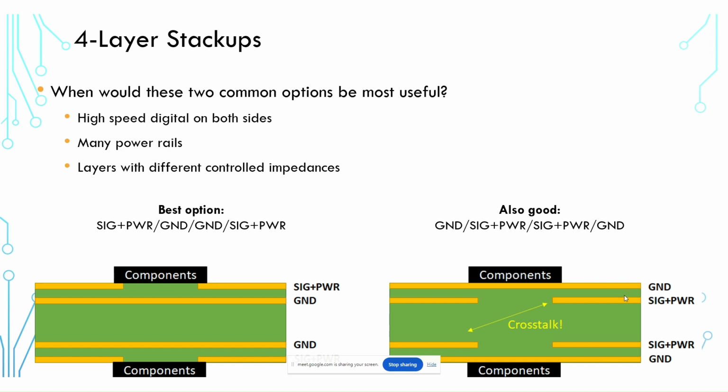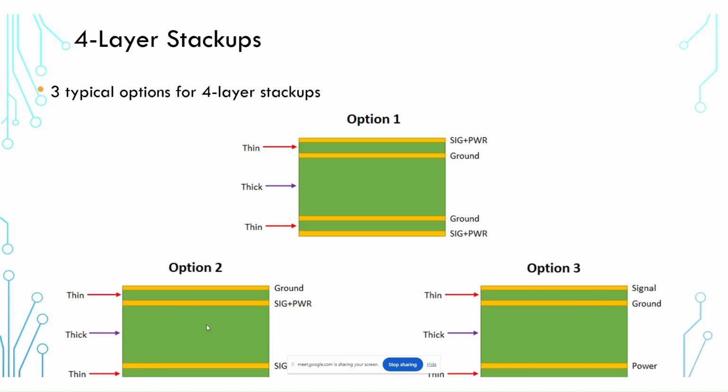And what you might consider doing is instead having a mixture of option 2 and option 3, where the top half is this ground and signal, and then the bottom half is power and ground. So this is another stackup that we recently discussed in a video. By doing that, you could then have that convenience of having a complete layer for power, just in terms of getting power to where it needs to go. You could break it up into multiple rails if you want to. And as long as you are not operating with extremely high frequencies or very fast signals, you can put those signals on this internal layer on layer 2, and those can route around to your components up on the surface.